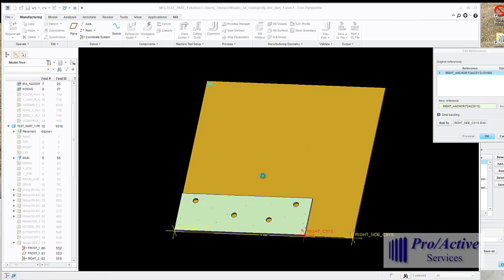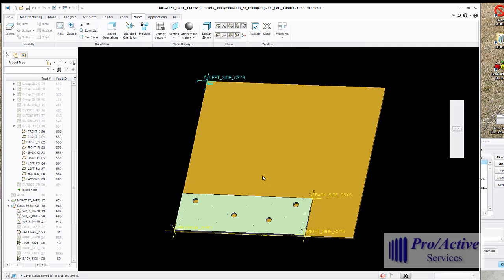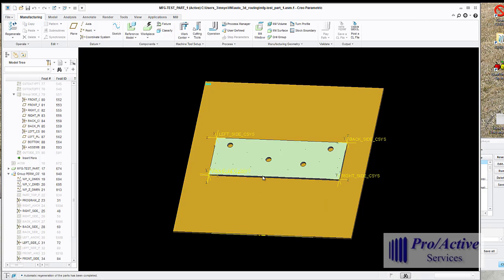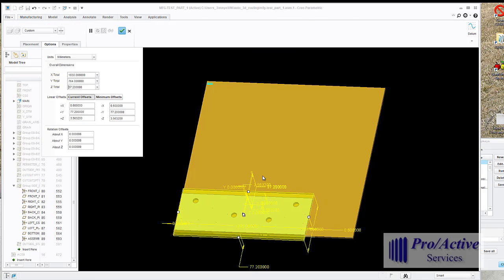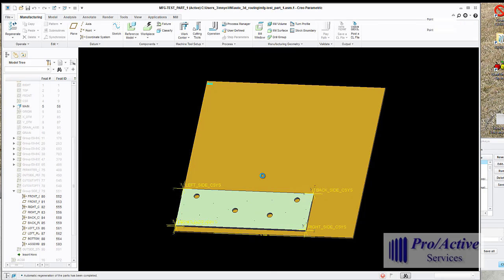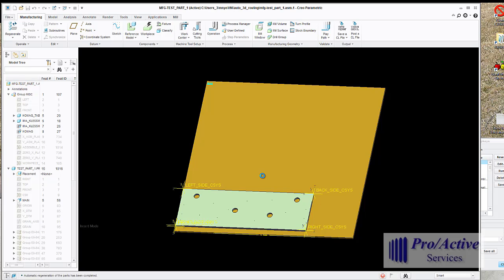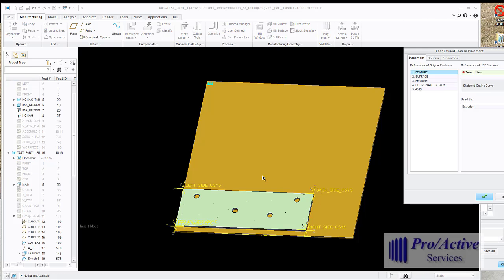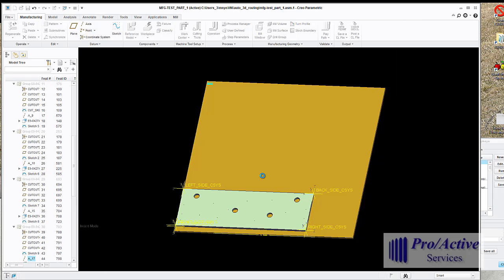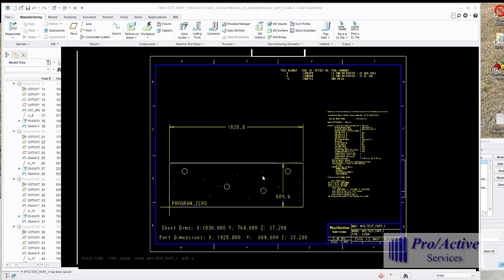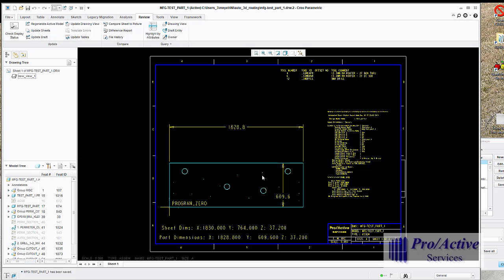This particular manufacturing model has a table for the particular machine that we selected. It's going to automatically assemble it. It's going to create some measurements. Based on the measurements, it's going to look at a table of valid panel sizes. Then it's going to proceed and program the part. Now it's executing the post, just generated the NC program, and now we're viewing the drawing itself.